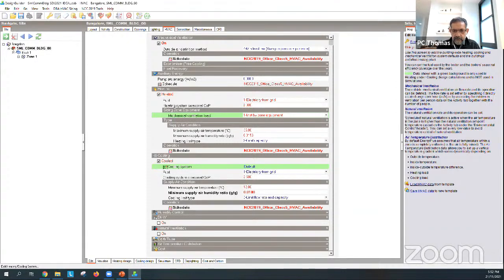So heat loss means your building fabric needs to be really good. The U value needs to improve, and improving means it becomes less, so the thermal transmittance becomes less. So it's a combination from there.